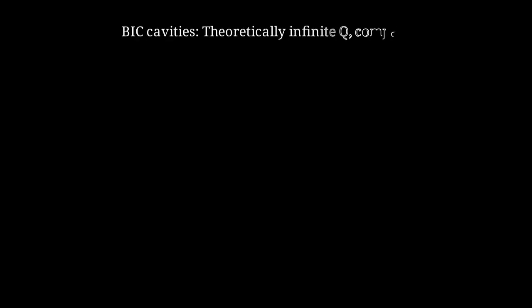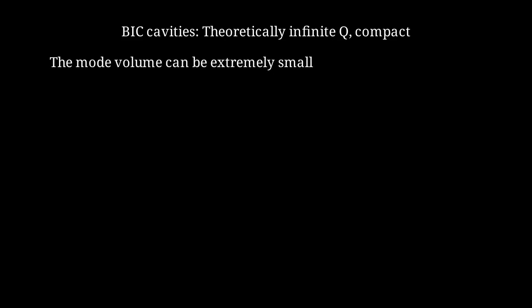Bound state in the continuum cavities offer theoretically infinite Q while maintaining compact size. The key advantage is that Q is not fundamentally limited by radiation, only by material absorption and fabrication imperfections. The mode volume for bound state in the continuum modes can be on the order of 1 cubic wavelength or smaller. Combined with high Q, this gives unprecedented Q over V ratios for enhancing light matter interactions.